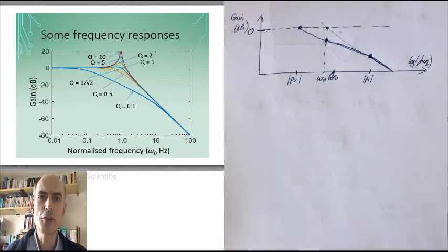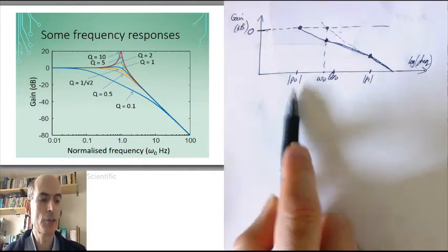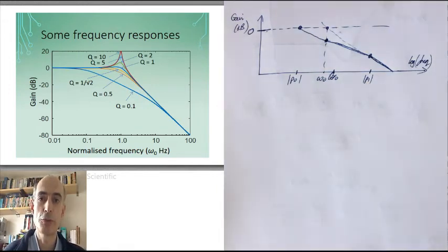Well, it is often useful to be able to calculate exactly where these pole break frequencies are. And you can do that from the resonant frequency and the Q factor. Not by solving the full quadratic equation, although that would work, but by using a much simpler approximate expression.